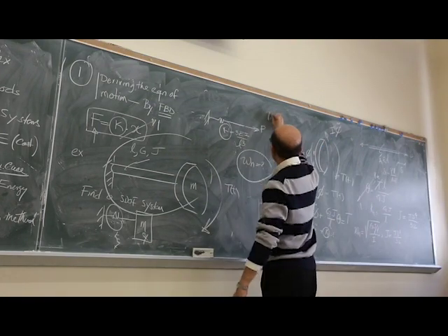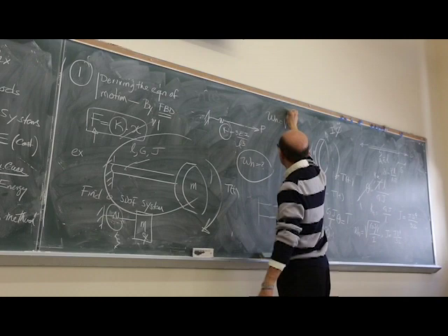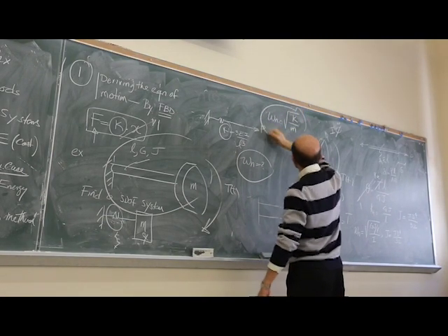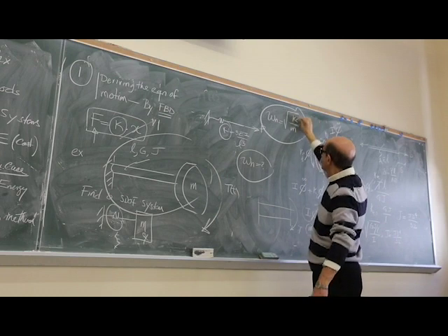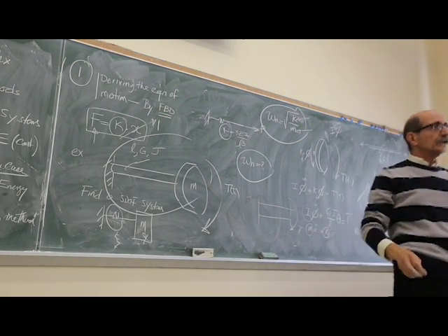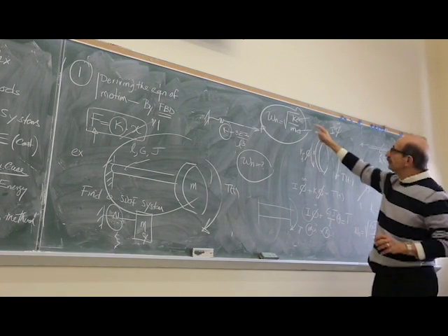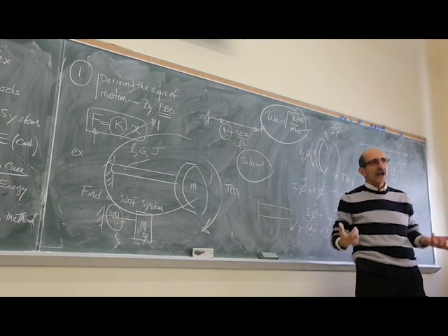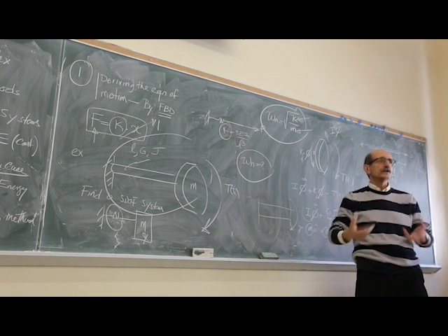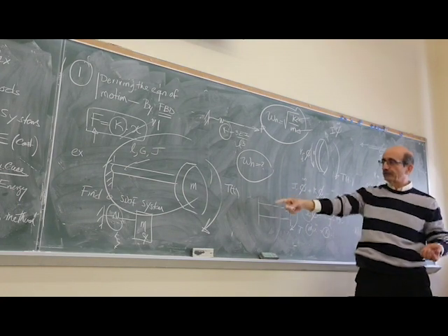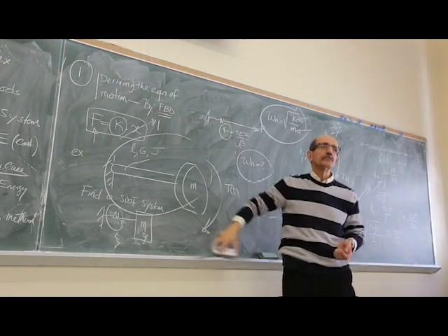Omega n, which is the natural frequency, is what? Square root of K over M. And what we are trying to show here is that this K and M are not a single component or single element, but they represent a lump sum of several actions or properties within that system. And that's what we are trying to find in order to set up this equivalent system.